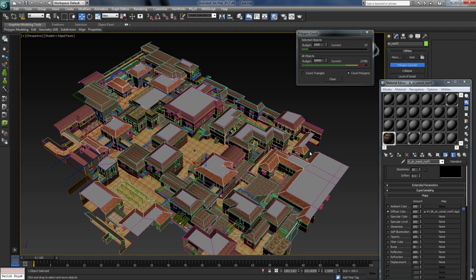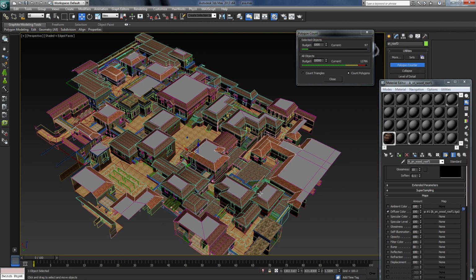A difficult point from this stage really is to start doing breakdowns, breaking things down into blocks, because as far as performance goes, the amount of triangles and polygons that we currently have in the scene is nothing. I mean, it's a joke. But we can further fine-tune the performance envelope by breaking things down into culling blocks. Now, culling, if you don't know, is when the engine doesn't see an object in the background behind another object, it doesn't render it.